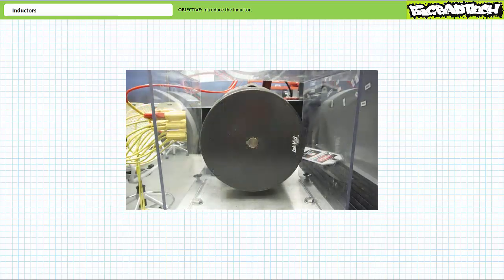If, however, a heavy flywheel is attached to the shaft, there is an amount of static inertia the motor must initially overcome. The moment the motor is energized, the shaft undergoes a brief period of acceleration, and after a period of time, it reaches the rated speed. The moment the motor is de-energized, the shaft doesn't instantaneously come to a stop, but rather the dynamic inertial load continues to rotate the shaft for a period of time before coming to a rest.